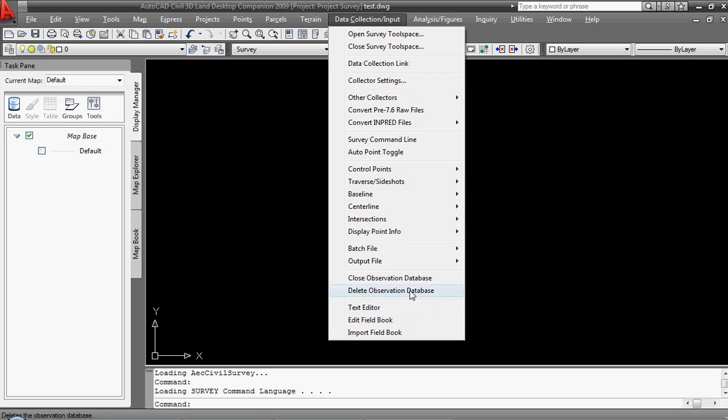At the same time, when we work in this environment, it's not a protected environment in that we're in the same general population as everybody else. So when we're attached to a land project, in this case Project Survey, the survey points that we construct are part of the same point database that everybody else would be working with as well. And that can create problems in that we're going to have engineers and surveyors and perhaps draftspeople and designers all battling over the same group of points, and you run the risk of somebody stepping on somebody else's data.